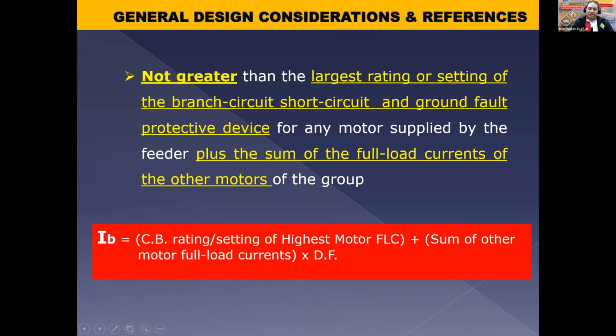And I know the wisdom because this is for coordination purposes, no? Coordination purposes na ito para ma-ensure talaga na during startup of this big motor, hindi ito magti-trip. And during startup na may loaded na siya and then biglang papasok si pinakamalaking motor, it's guaranteed na, or it's not really full guarantee, but at least it can give you an opportunity na hindi ito mag-nuisance tripping, no? Kaya nga ginamit yung circuit breaker rating na, not the full load current, no?